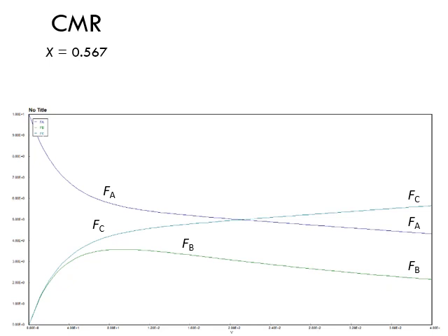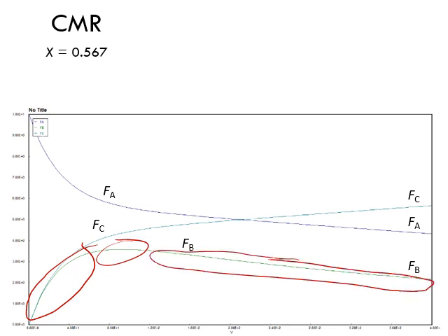That is because A is a reactant, and the molar flow rate of C is increasing because it's a product. So as the reaction progresses, as we go down the length of the reactor, A decreases, C increases. But we have something really interesting here. What's happening to FB, the molar flow rate of the hydrogen? Well, first it's increasing, right? First it's increasing, and then it reaches a maximum value, then it decreases. Why do you think this is happening?